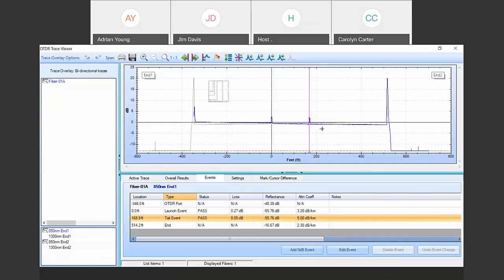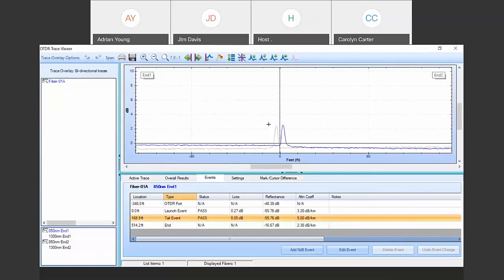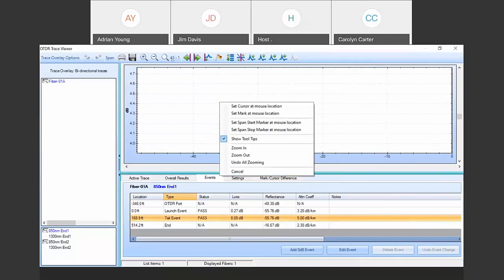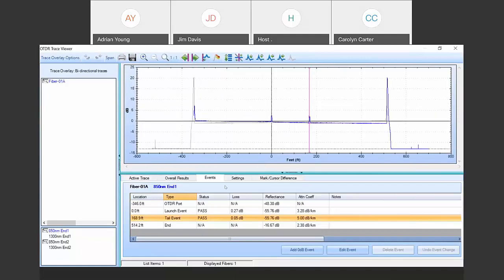To save us having to go out and visit you, again, send us that FLW, and that will help us to understand the nature of the failure. Again, I'll say let's start with cleaning and make sure we have a camera, even a handheld microscope, to check the fiber end face, and a cleaning kit, because that's going to be the first step.